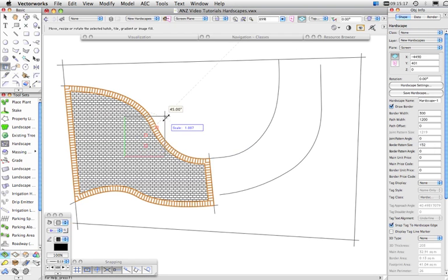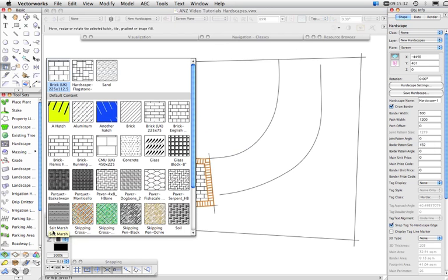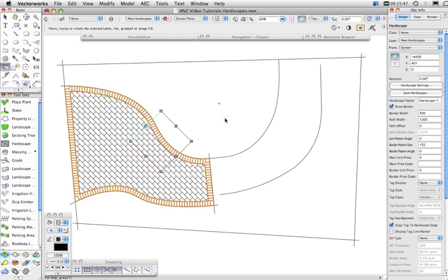If I want it to be twice as big, I just type 2 and hit enter, and when I click again the hatch will be twice the size, and the name here will have turned blue because it's indicating that this hatch is actually edited. It's been edited by the attribute mapping tool. If I put the cursor over one of these center points, I also have the ability to rotate the hatch. Okay, so that's what you can do when you apply an attribute from out here.